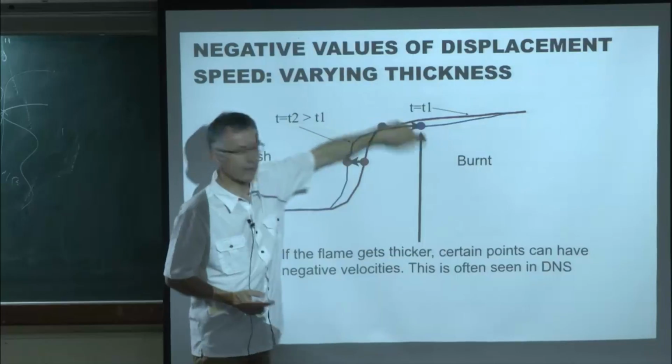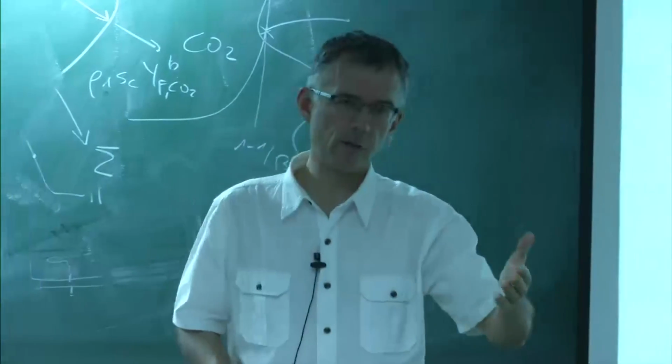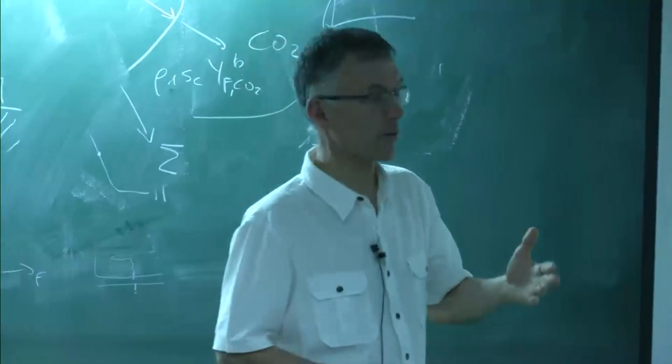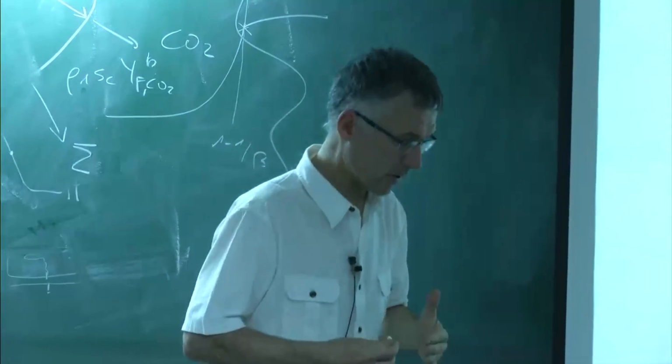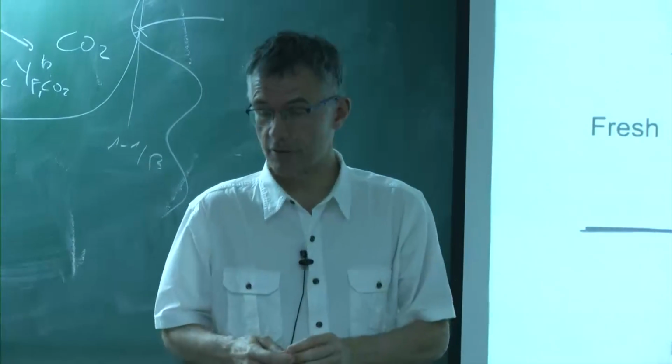So this point would apparently go, not against the flow, but in the same direction. So that would correspond to a negative displacement speed. Instead of moving forward and eating the fresh gases, it would be pushed away by the fresh gases.